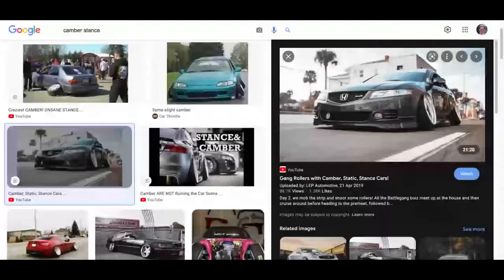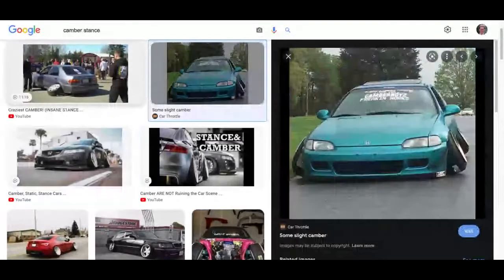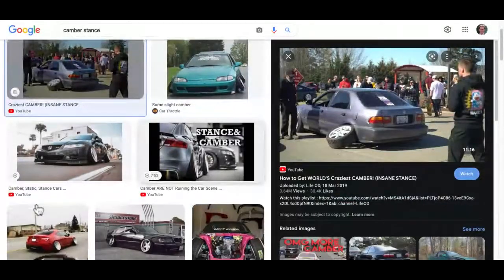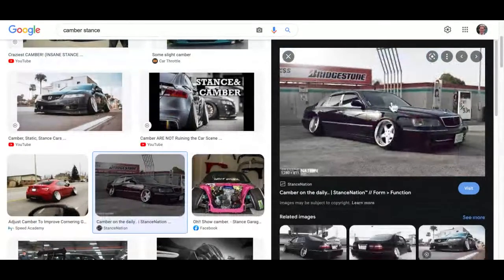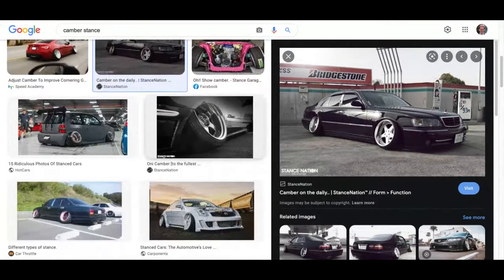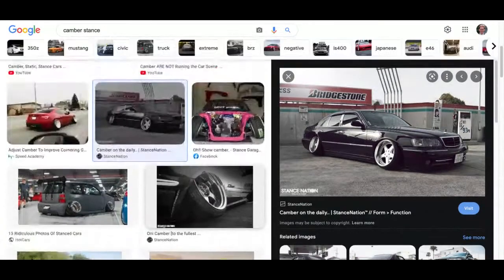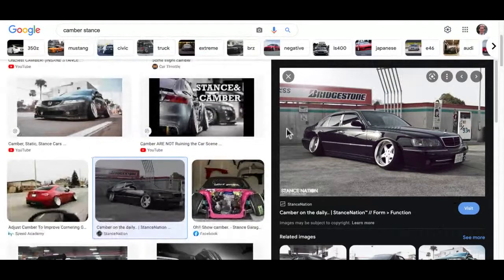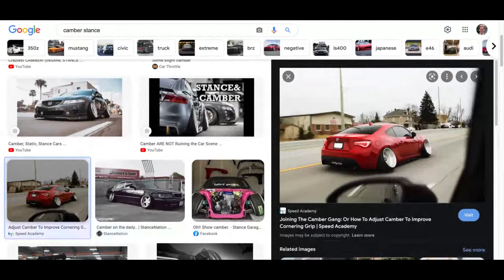So you see these sort of ridiculous setups of vehicles with ridiculous camber angles. I mean, that just looks broken, doesn't it? You can see that. Obviously, one of the big issues with this, and this is reported by the student who had a Volkswagen Jetta with a similar setup, was that the tyre wear was unbelievable. You just got this pattern. And obviously, it also ruins handling. Engineers spend millions and millions of pounds optimizing handling, and then it gets ruined by people who do this sort of stuff.